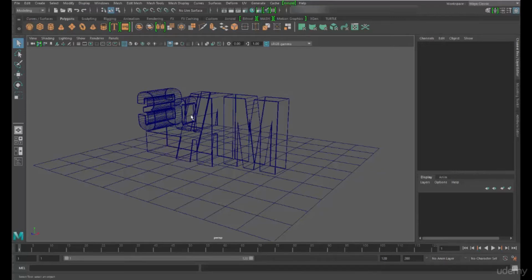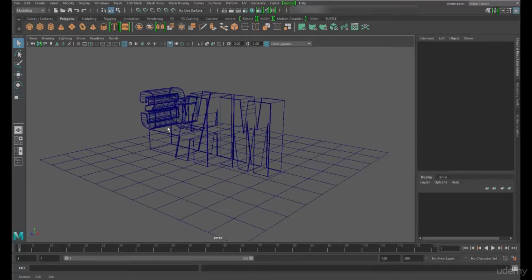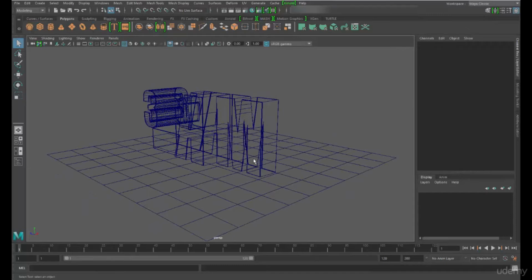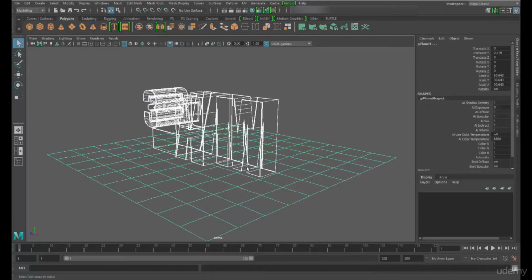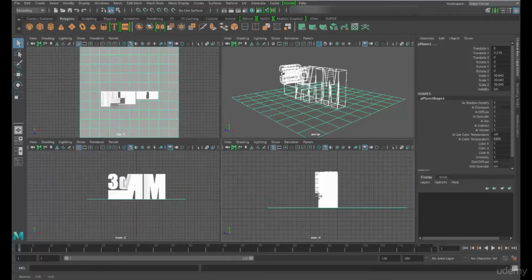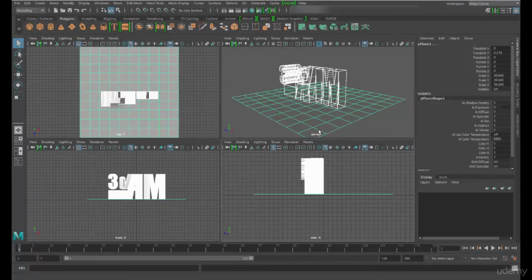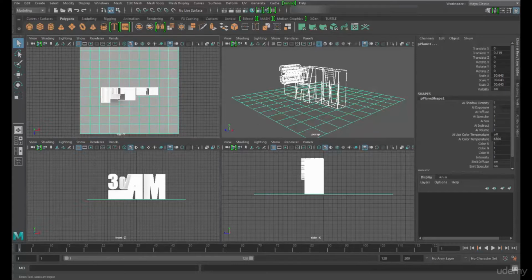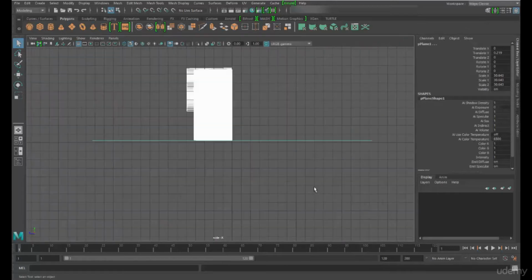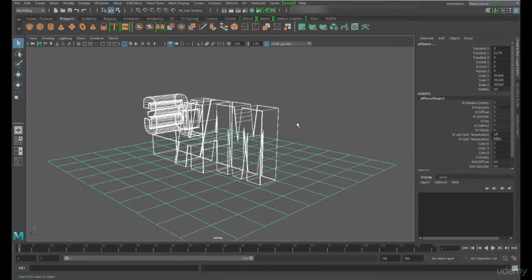Let's have a look at viewports. Mine starts with a default perspective window, and we're currently viewing a scene model of a logo in wireframe. The viewports have different viewing options inside each viewport. We can move around the viewports using the Alt and mouse button configurations, and we can blow up or enlarge the windows by hitting the space bar as we move through.